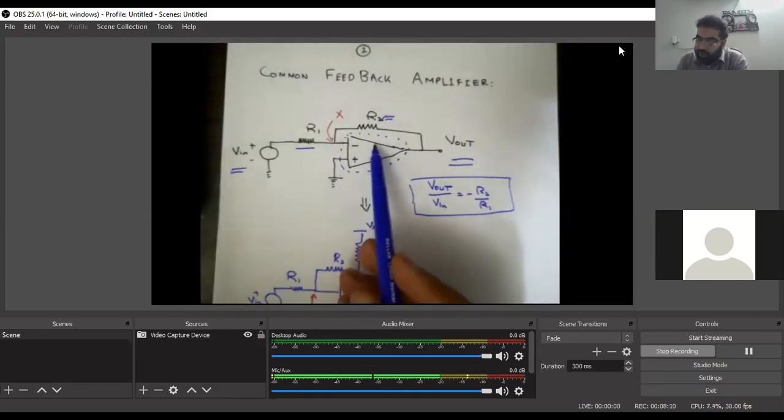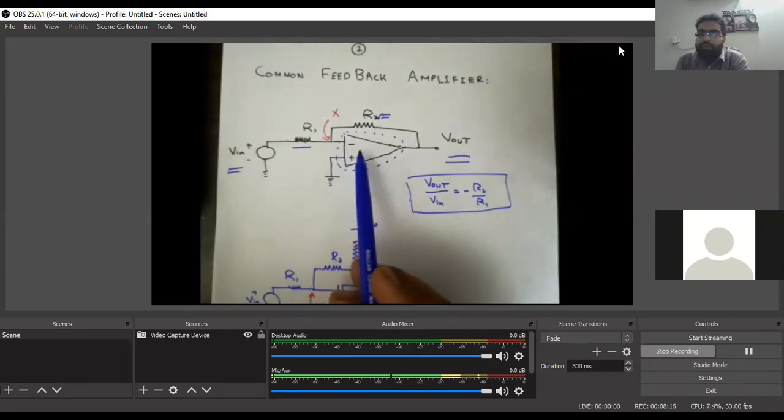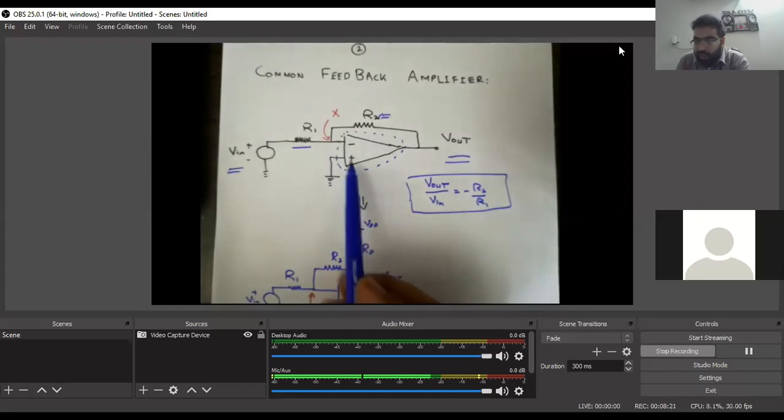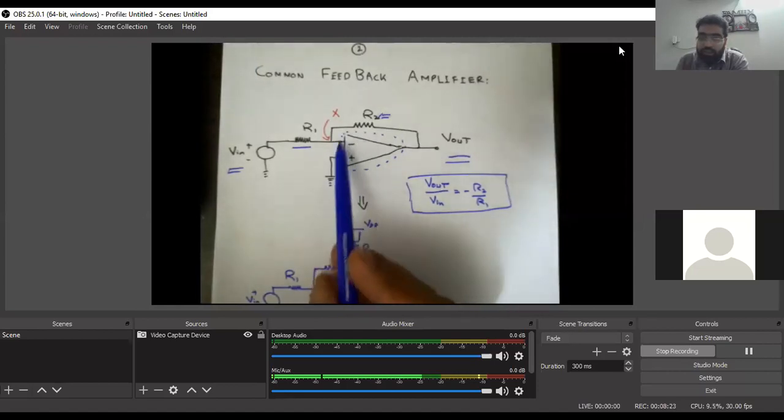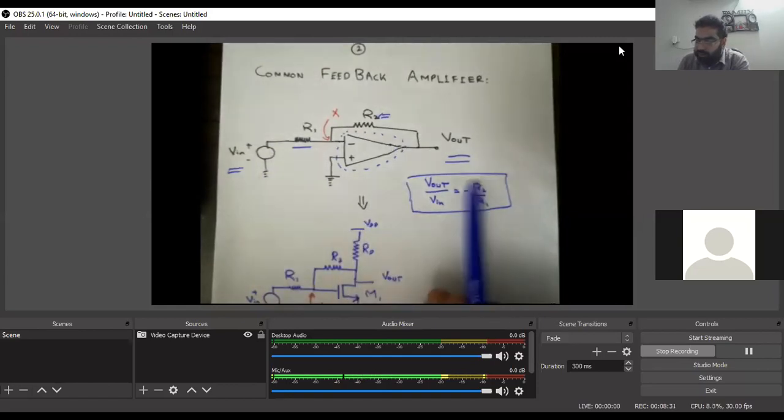Previously, we were talking only about what's inside the dotted curve. Till now, we have covered how we can design an amplifier with a high gain, with the multi-stages, with the cascade and all of those things. But we were only talking about this dotted structure. And this dotted structure has to be stable itself, but on top of it, the closed loop system, which is consisting of minus R2 over R1, should also be stable. That we are going to see today.